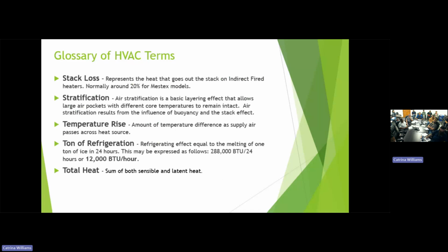Talk about air turnover, getting rid of stratification. Within 30 minutes, the floor to ceiling temperature difference in that building was 5 degrees. All that heat, that temperature up there, is wasted. Back down at the floor level, we're still using that. So it cuts the heating bill down. Everybody's more comfortable. In some cases, like a pharmaceutical warehouse, they can't have stratification. They have to have even temperature throughout. So it helps the product in some cases as well, besides creature comfort, and it's energy efficient.